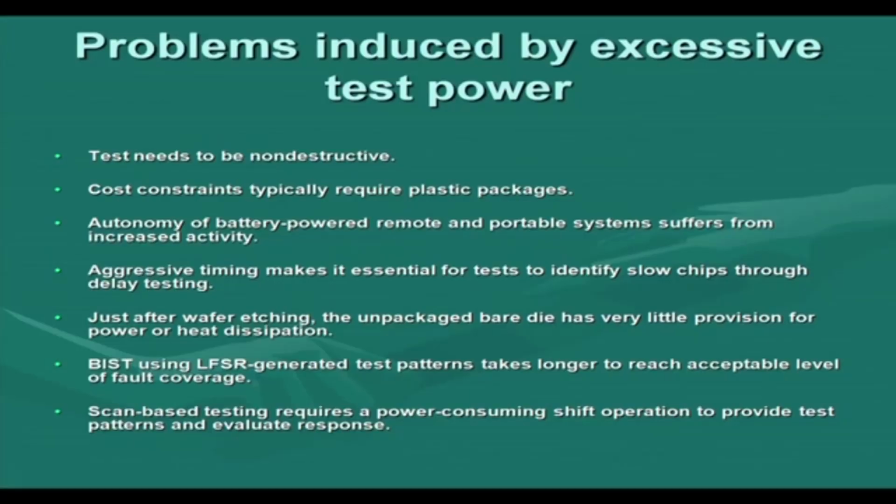In the real operation, whatever is the fault simulation result, say for getting 95% coverage, it shows that the LFSR has to be run for 10,000 cycles. So, in the actual run, the LFSR has to run for 10,000 cycles, but out of these 10,000 cycles, many times it generated patterns which are not detecting any new faults. Still, since we cannot skip over the LFSR's output, we have to generate those patterns, and that will be consuming power. Those patterns are to be applied to the circuit, so that will consume power. So, this is one issue with the BIST testing.